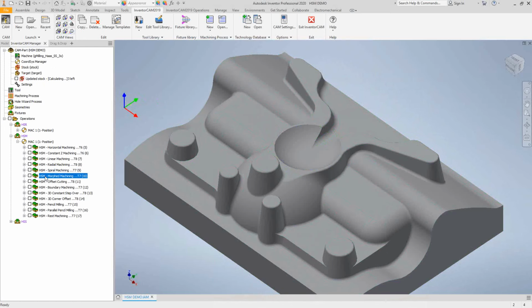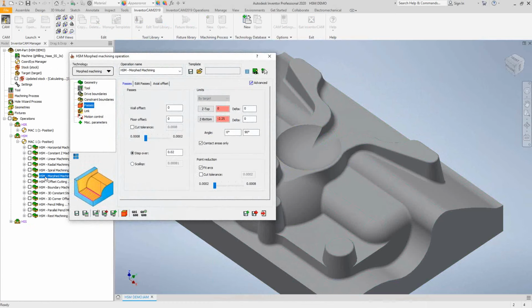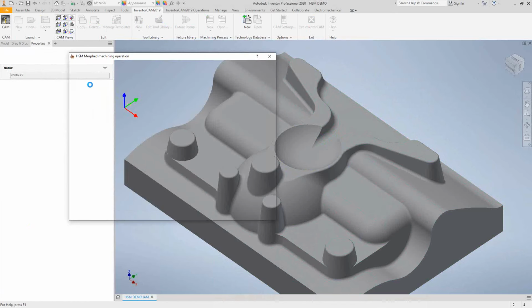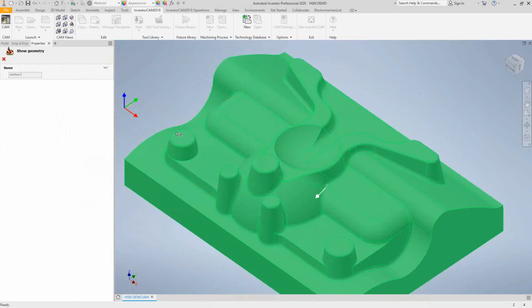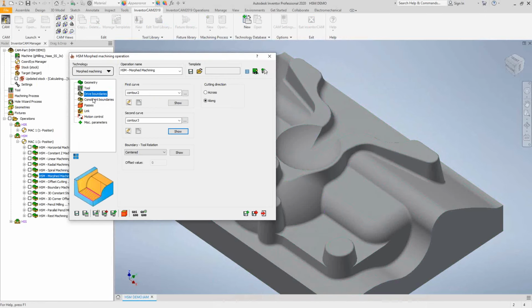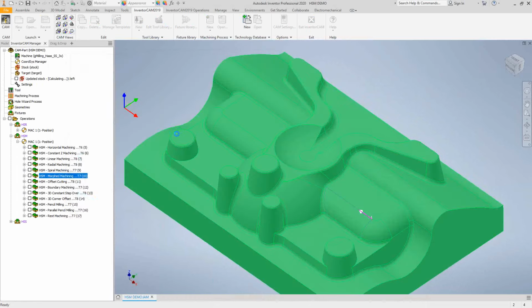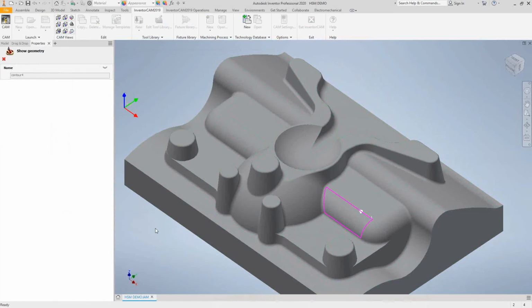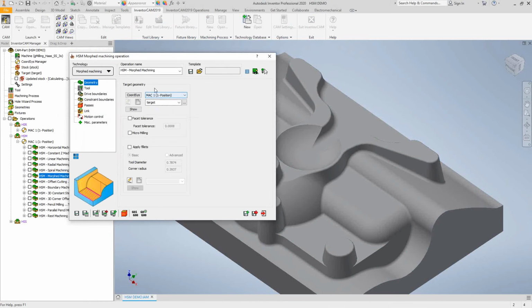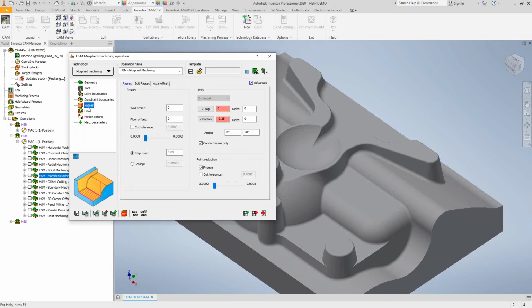Morphed machining, similar to morph between boundary curves like we saw in video 12, is the HSM version where we give it drive boundaries, in this case, a start curve and an end curve, and then we constrain the movement of the tool to just that one surface. So it's going to blend between the start and end curve just along that surface. It's still a surface-based toolpath, but by giving it a constraint boundary, I'm basically telling it, apply this toolpath but to only that one area in between that sketch.